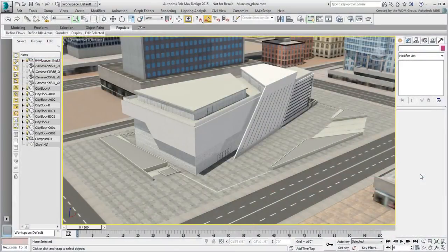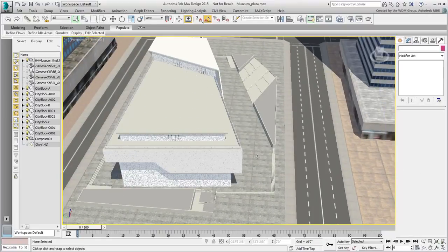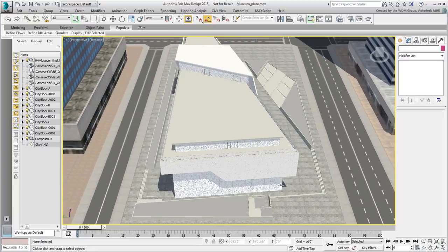In this movie, you continue working on the plaza, adjusting more materials and adding a few trees. Continue working on your file from the last movie or open the file named museumplaza.max. As you did before, you take a look at some materials transferred from Revit and adjust them if and when they need it. Start by taking a look at the grass areas.